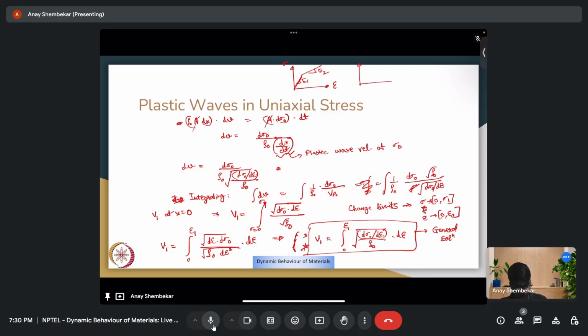Then you also have your power law constitutive equation and stuff like that. So based on each particular constitutive law, you could do a numerical integration wherein if you have the experimentally available data, you could figure out the numerical derivative d sigma by d epsilon at each value of strain, and then take the density as constant and then integrate it for each incremental strain value.